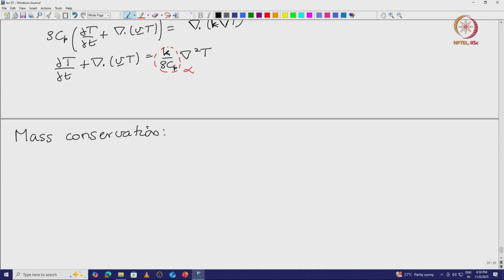For the total fluid density, that is partial rho by partial t plus divergence of rho times V is equal to 0. Okay. This is for the total fluid mass, this is not for a particular component. Okay. So, the condition that total mass has to be conserved, right. Mass can be converted from one form to the other, but the total mass has to be conserved, except in the exceptional cases when you have conversion between mass and energy, okay, in nuclear reactions and so on. So long as you do not have conversion between mass and energy, total mass has to be conserved, and therefore,